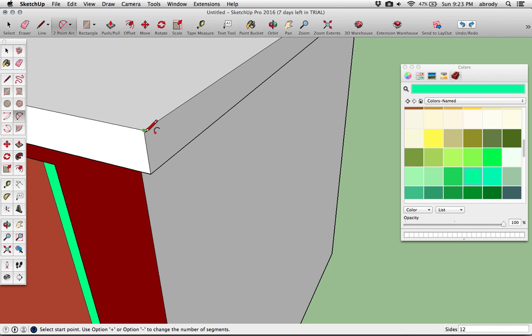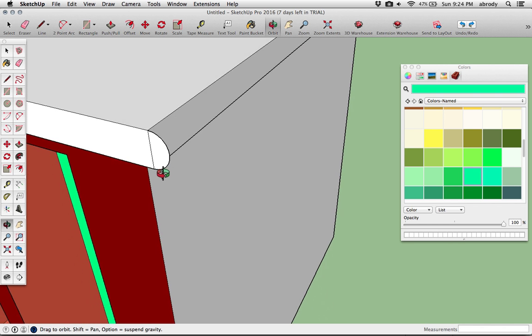Now, in this case, I'm just going to make it a nice rounded nose, which they call a bull nose. And I'll do that by drawing an arc. Now, the thing about arcs is, and this is true for most commands, if you look, there's a red line indicating I'm on the red axis. You have to be very careful with arcs because they can go in any axis, just depending on which way your cursor is going. If I go this direction, I get a green indicator from my cursor. It's making an assumption, or an inference, that I want to go in that direction. Make sure you click when it's going in the direction that will draw the arc in the correct way.